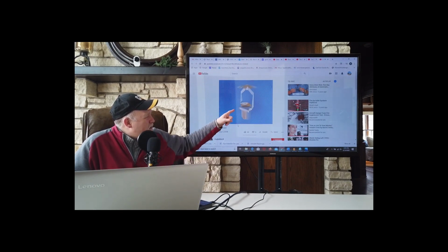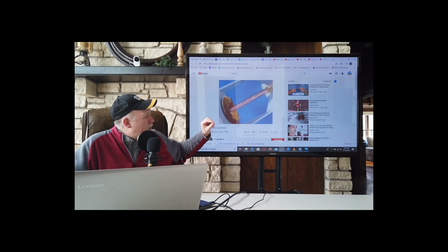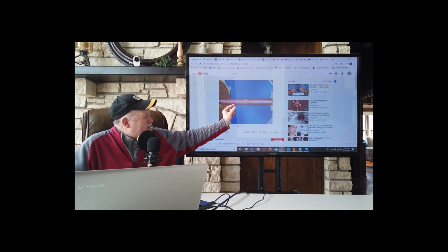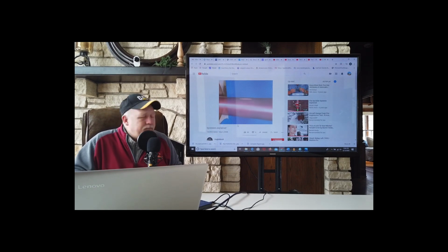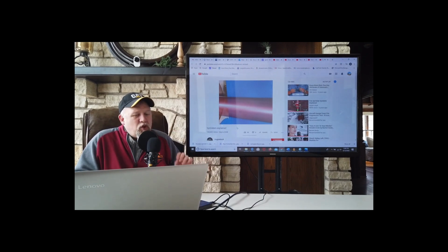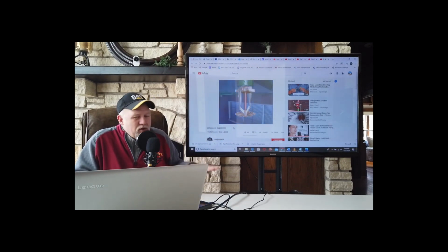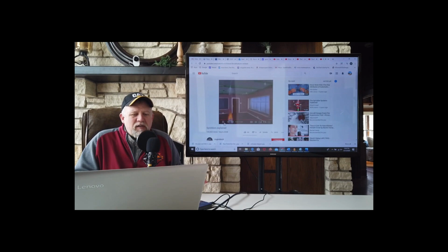The glass piece holds this stopper in place. It's got a little bit of an air bubble in there, and that liquid, as it expands, it'll compress the air bubble, and then once it can't compress anymore, as it expands, it'll crack that piece of glass. Piece of glass is cracked, water pressure does the rest. If this was a dry pipe system, first, the air would come out of there, and once that air pressure drops low enough, it's going to cause water to flow through the system after that. All right, back to the handout.